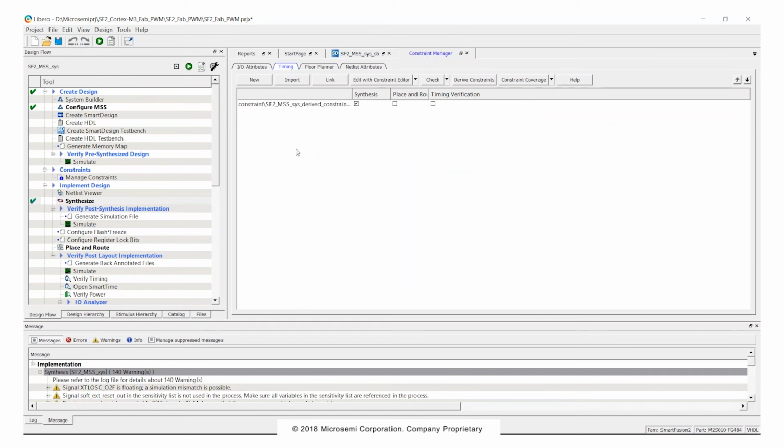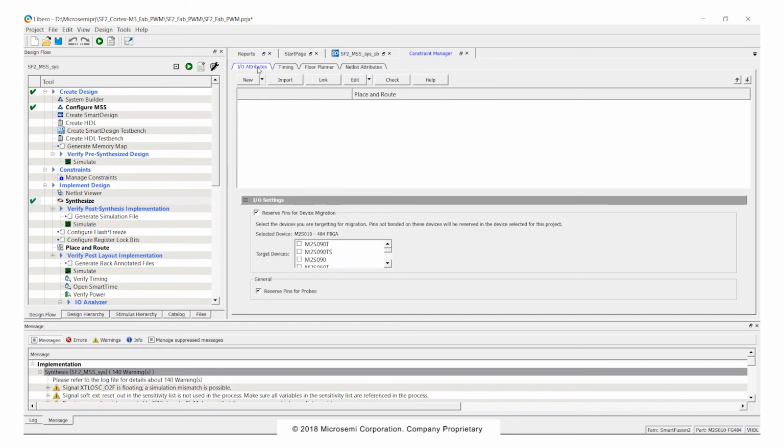And if you create a new project from scratch, but you forget to choose the enhanced constraint manager, then you'd have to start over again. So there is no switching from the classic constraint flow to the enhanced constraint flow. You have to make that choice when you create the project, and then you can move on from there.